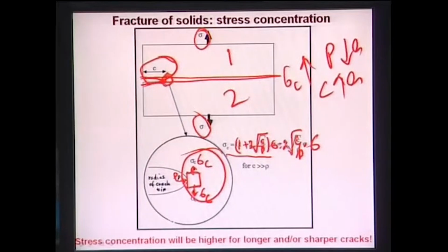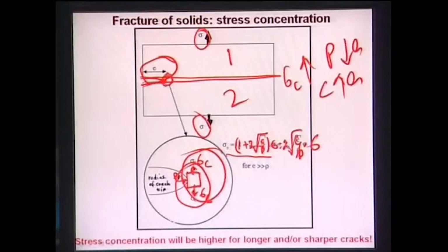Now the question is, this kind of thing also happens in metals, so why do metals not fracture so easily like ceramics? The answer is that at this growing crack tip area there is dislocation motion, and that dislocation motion leads to the yielding of the material. Yielding means the material will be plastically deforming, but in ceramics that plastic deformation is not possible, and as a result ceramics can be easily fractured into two pieces by simply the crack propagation.